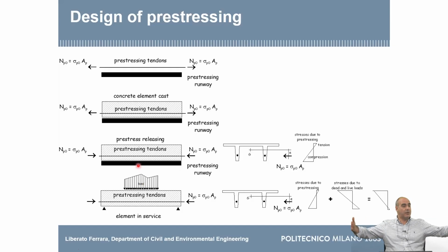At the two edges of the pre-stressing runway, you have two small walls with thick steel platens, which serve to anchor the pre-stressing tendons. On one end, they are fixed. Okay, you have holes there and you fix with some devices the pre-stressing tendon. On the other end, you have your jacks that apply, in this case, the pre-tensioning force to the tendon.